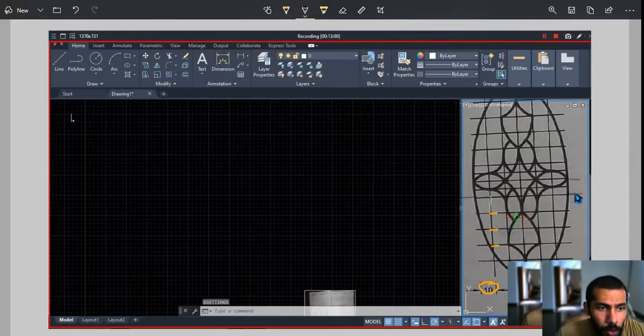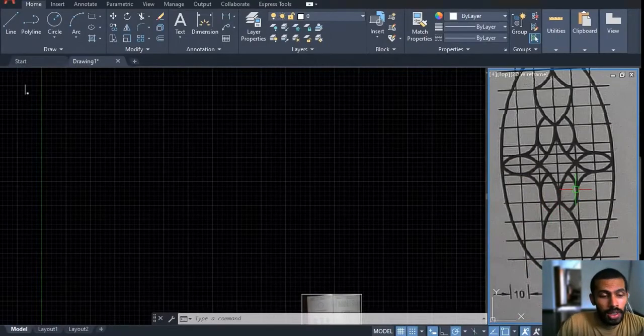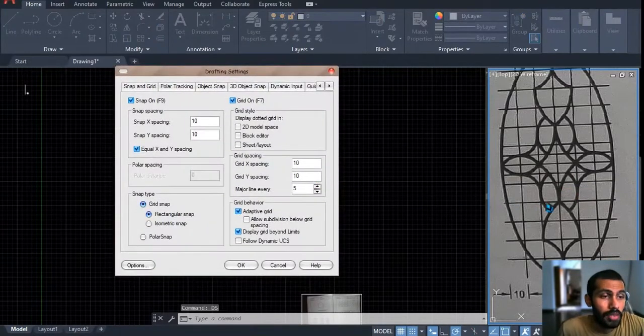But you know, unfortunately there is a point right in between. There's a snappable point right in between, so I have to give the spacing of snap exactly half of 10. Okay, if not, I might not be able to pick any point in between. I can't pick this point here, so that's why I'm gonna give the snap spacing to be 5.